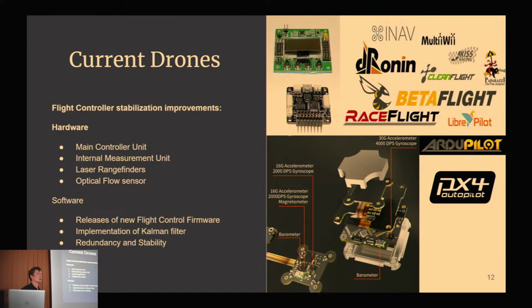What also was introduced to the drone community back in 2012 to 2016, most of the toys available in the day were equipped with optical flow. What people did, they put a very, very small and not very high resolution camera on the bottom, and they wrote a very simple optical flow recognition. Based on that sensor, people were able to make the drone hover even when the bottom, for example the floor or a table, was not even, making it possible for the optical flow algorithm to stay in one place and detect any movement and shifts from the ground perspective.